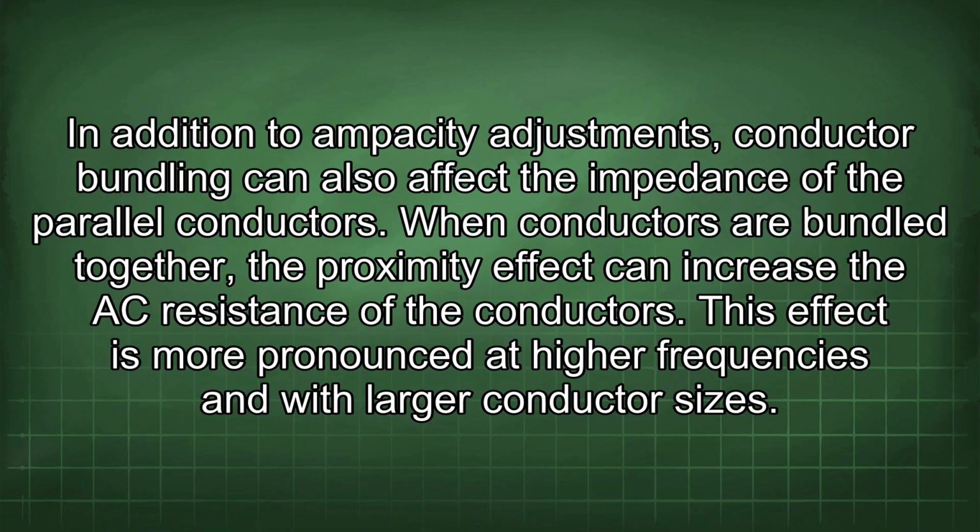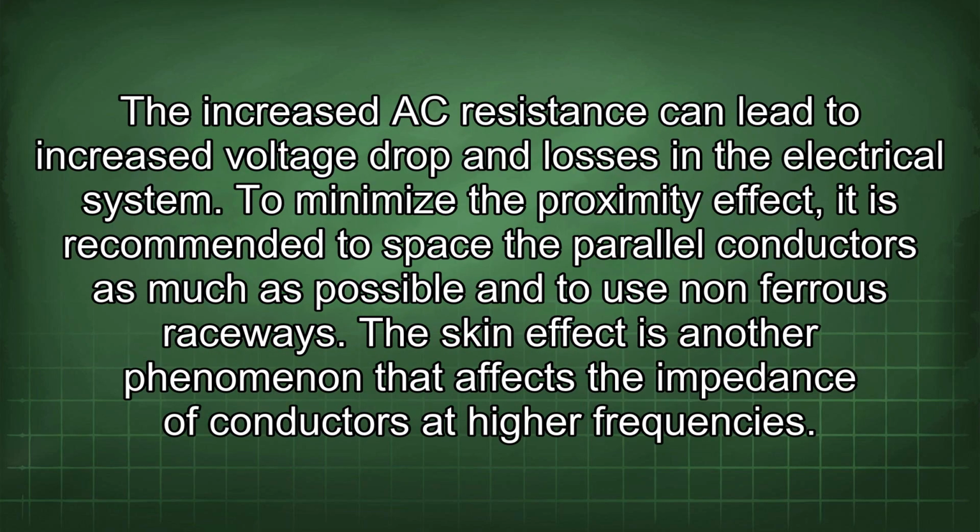In addition to ampacity adjustments, conductor bundling can also affect the impedance of the parallel conductors. When conductors are bundled together, the proximity effect can increase the AC resistance of the conductors. This effect is more pronounced at higher frequencies and with larger conductor sizes. The increased AC resistance can lead to increased voltage drop and losses in the electrical system. To minimize the proximity effect, it is recommended to space the parallel conductors as much as possible and to use non-ferrous raceways.